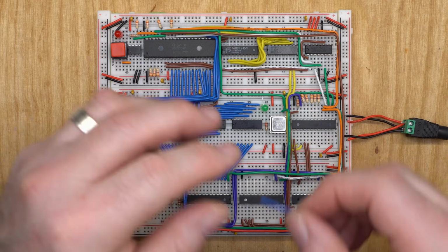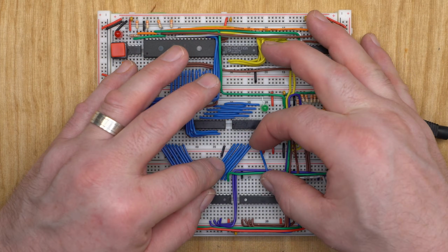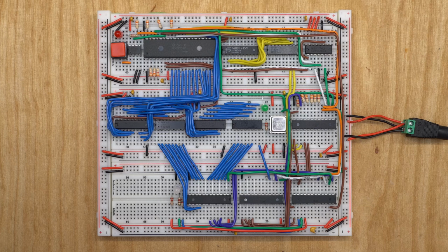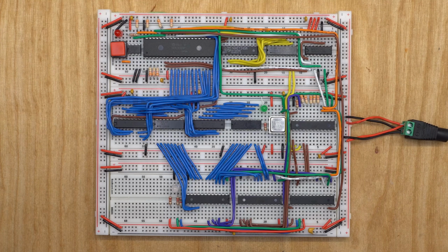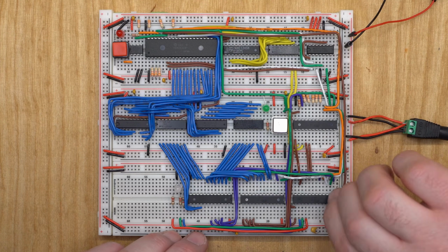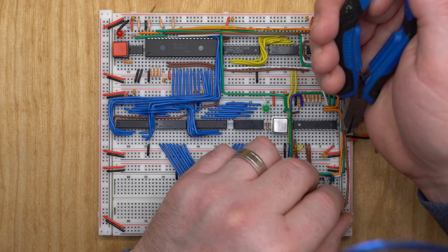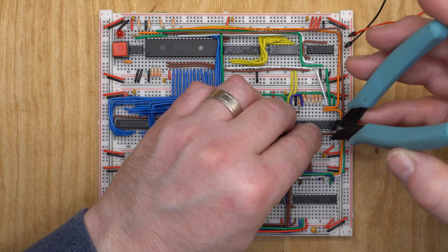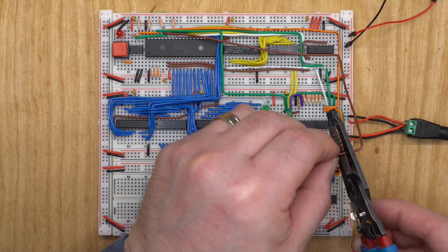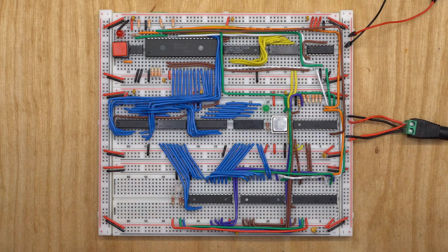I/O decode gets the lower address lines, meaning A0 through A7 on pins 4 to 11. And finally, remember the misconnected MRDY line? We fixed that and connected to wait state gen pin 23 where it belongs. And that's it. All that's left is to test the PLD logic.